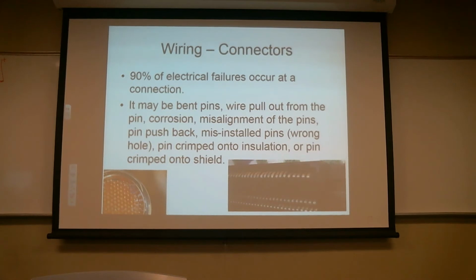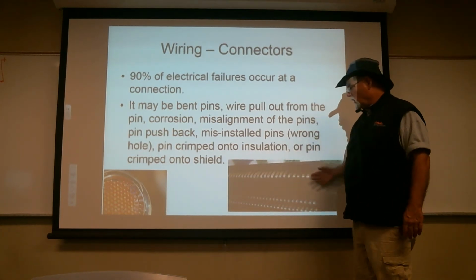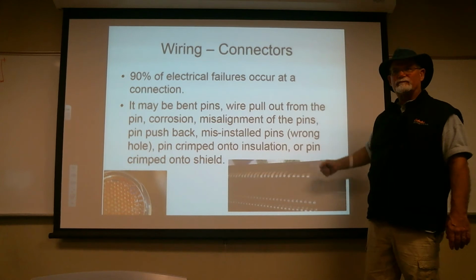I will tell you that the preponderance of electrical failures, and I made a lot of money off them, I don't know if it's 90%, but it's up there, either occur at this end, the pin end of the connector: pin misalignment, corrosion, pin pushback. Like I just fixed a radio that had pin pushback. Or out on the other end, the wire breaks off.